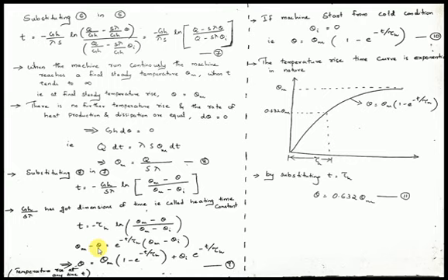So you must be thorough with these two relations. In fact, you must learn by heart these two expressions. That is the expression for temperature rise, the standard expression, which is represented by equation 9 here. That is theta is equal to theta m into 1 minus e raised to minus t by tau h plus theta I e raised to minus t by tau h. You must learn this relation by heart, and along with that you must know this relation also. That is the equation for final steady temperature rise, that is theta m is equal to q by s lambda. These two expressions you must learn by heart, then only you will be able to solve the problems related with this.